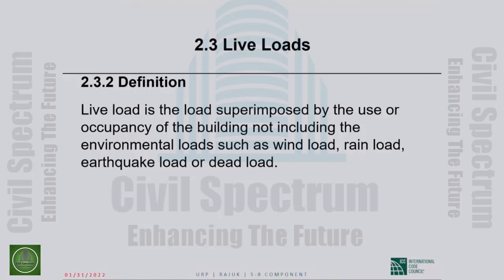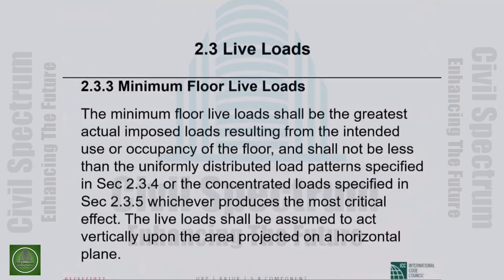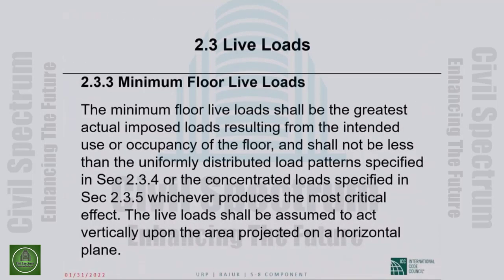Superimposed, why it says super, I don't know, I would have said imposed by the use or occupancy of the building, not including the environmental loads such as wind load, rain load, earthquake load, dead load. So dead load is not an environmental load. Why they wrote it here, I don't know. But anyway, live loads are exclusive of those. Now, minimum floor live loads, I think I'll skip the writing here.